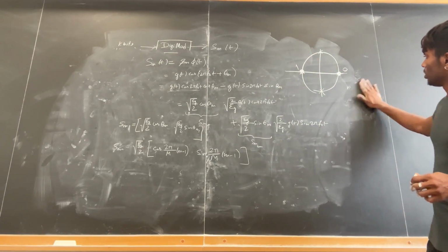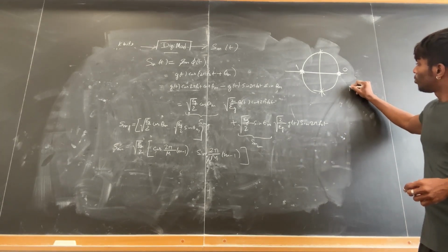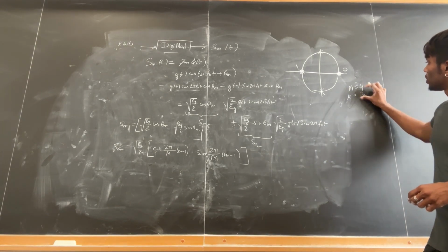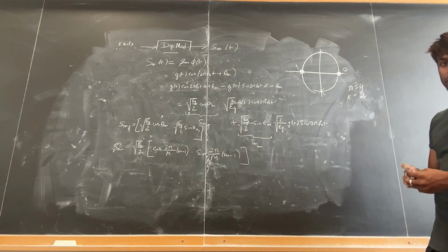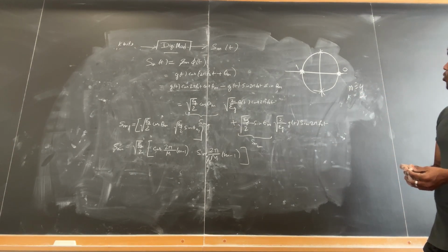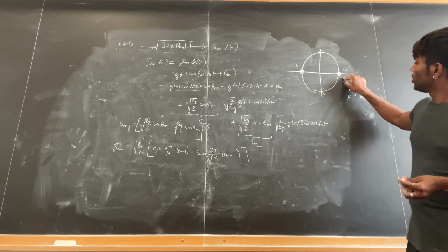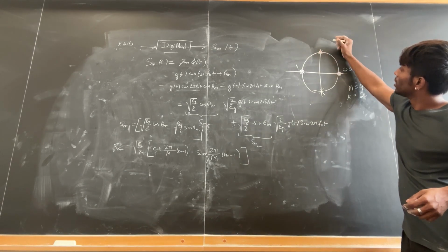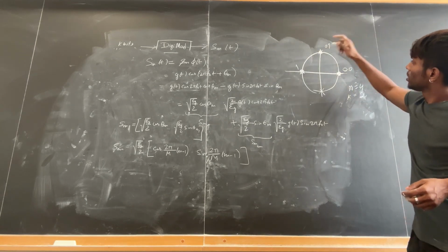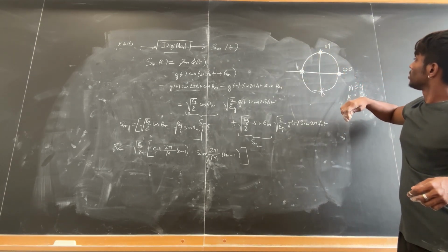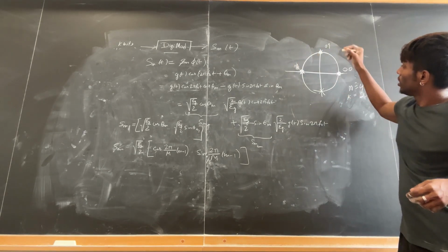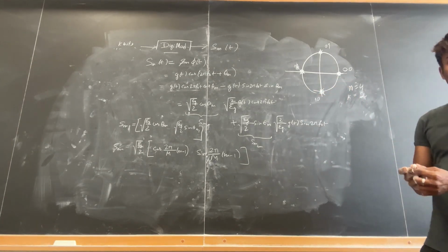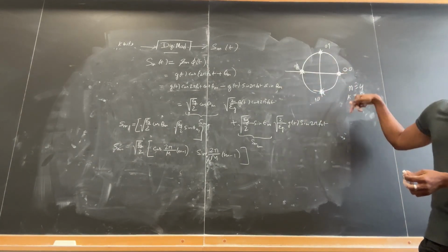Now we are expanding on m is equal to 4, that is k is equal to 2, 2 bit representation. So there will be 4 symbols. So the first symbol will be here, that is 0, 0. The second symbol will be here, that is 0, 1. Third symbol will be here, that is 1, 1. And the fourth symbol will be here, that is 1, 0. So that is the idea of phase shift keying.